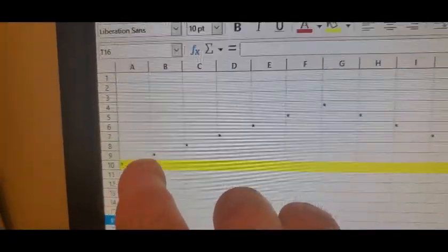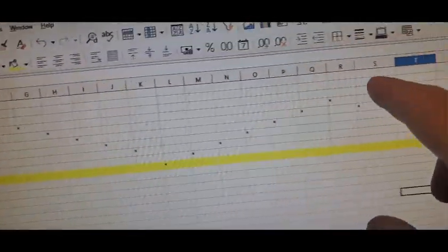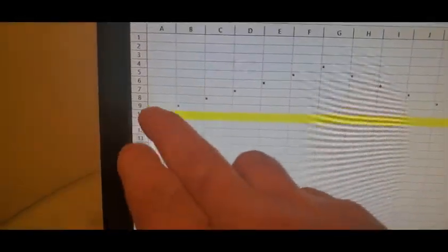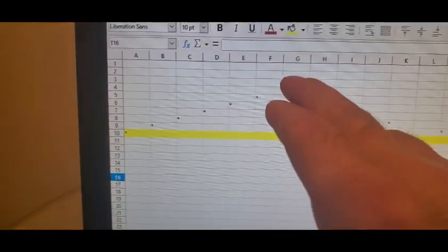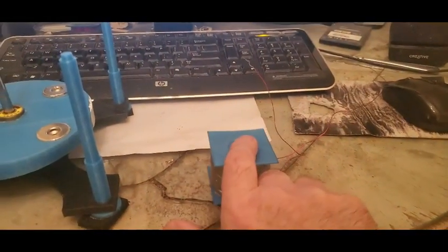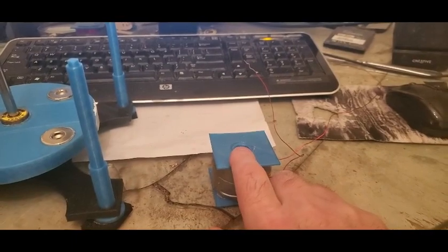And then you do it again, the same polarity of current into the coil, and again and again. And here's my incredible graphing skills. So just to make it a little graphical, the current is going like this. The yellow line is 0. Boom, back to 0, boom, back to 0. So in this case, there's not really any need to use a full wave bridge rectifier because you're not putting alternating current into the coil.